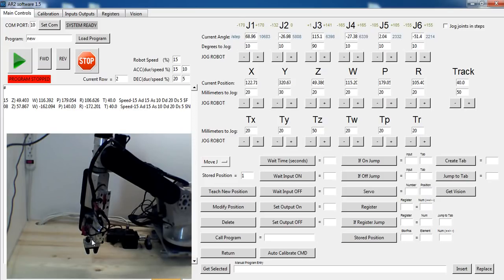I'm getting into a point where the kinematics that control the XYZ, yaw, pitch, and roll don't know that this wrist config is going to change, and then your moves might start getting a little bit irregular, and then you'll have to recalibrate the robot.